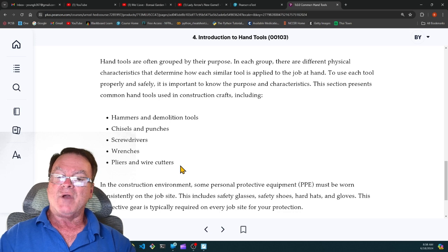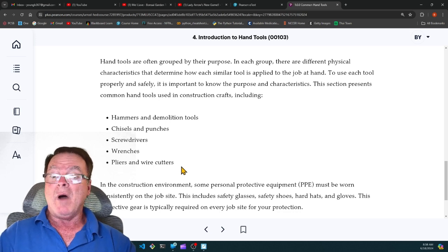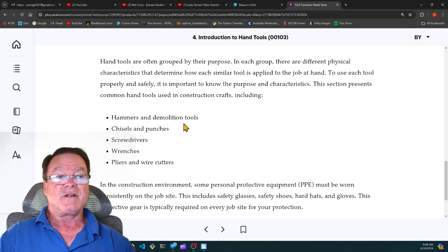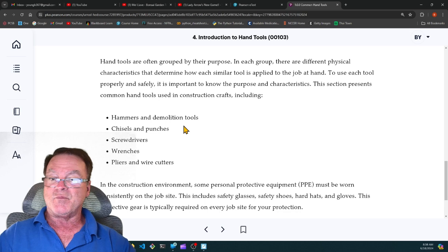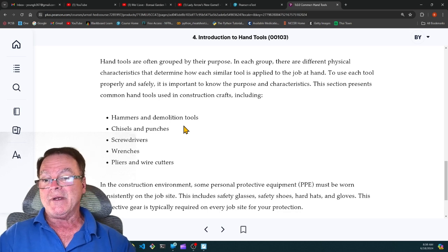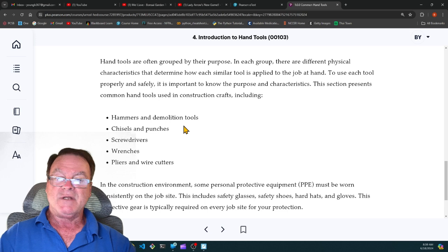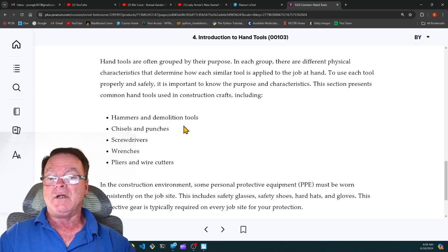A lot of times you'll go into an existing building that they're remodeling. That's where demolition comes in. Sometimes you have to determine what to take out: receptacles, lighting fixtures, what have you. Sometimes you'll turn off a circuit, pull out the wire, and remove the piping. A lot of times after you disconnect the power and take the wires out, they'll just come in with sledgehammers and take the wall down, depending on what the wall's made out of.